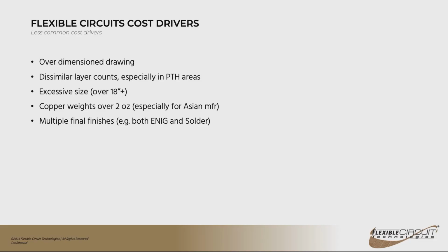The question is, flex solder mask or coverlay? What is the best option? That's a good question. If you are going to be bending your circuit sharply, you need to go with coverlay. Flexible solder mask doesn't mean that it's super flexible. It just means it's a whole lot better than the stuff you put on rigid boards. But it will crack if you bend it too sharply. So if you are going to be bending it sharply, you definitely want to go with coverlay.